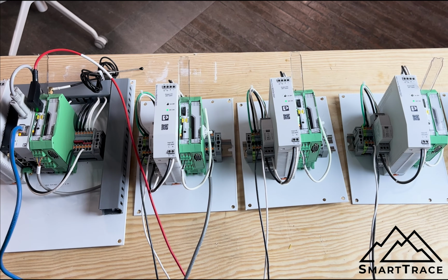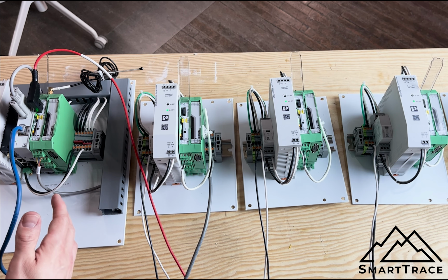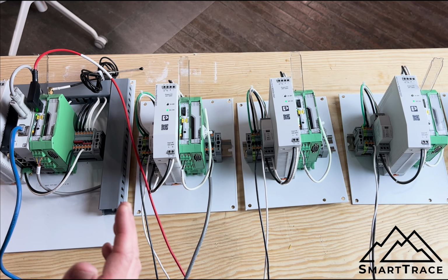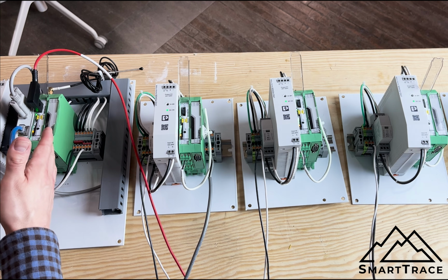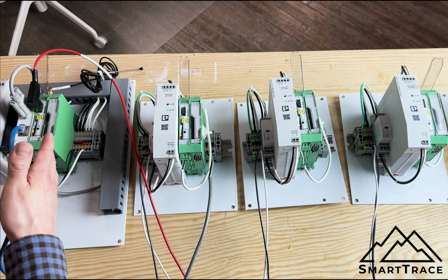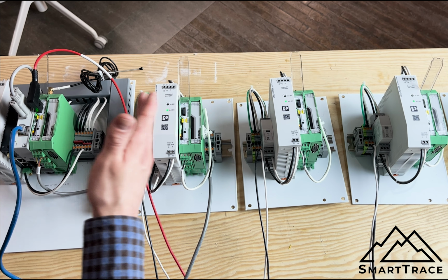Okay, this video is going to describe how we could diagnose an existing radio network that is already installed. So the simulation that we have here is on our test bench. We have a master RAD900 Phoenix radio, and we have slave radios. And this application, I should have mentioned before, is simulating a heat trace communication network utilizing serial communication transmitted over 900 megahertz signal using the Phoenix RAD900 radios.